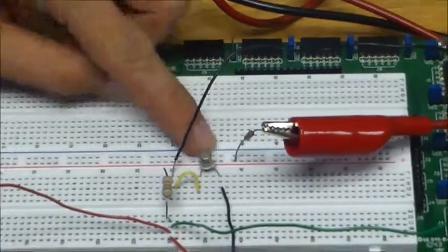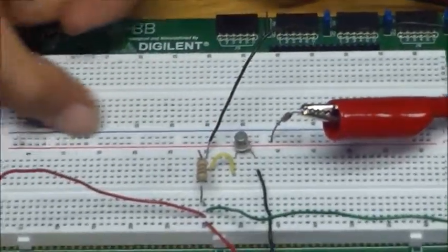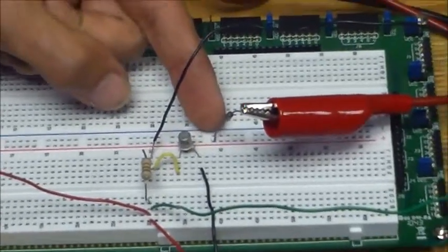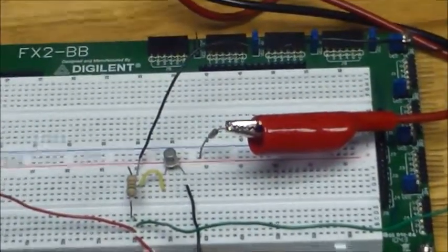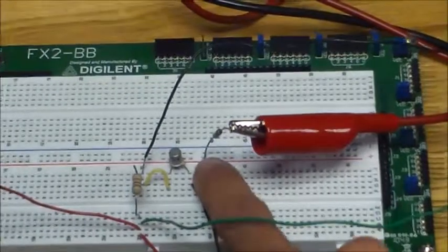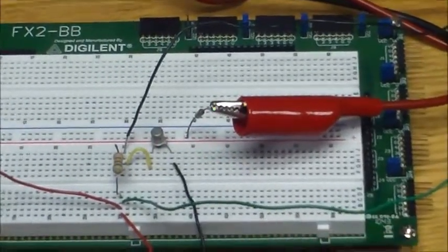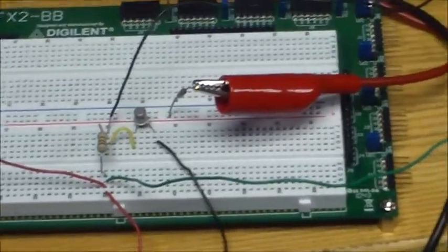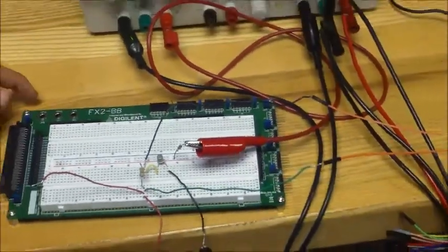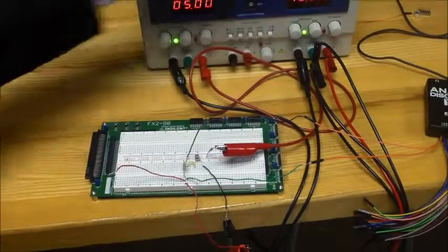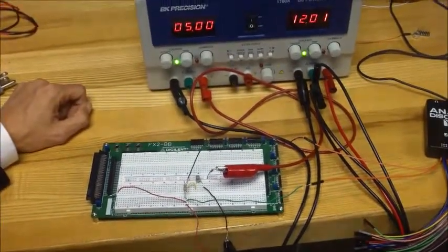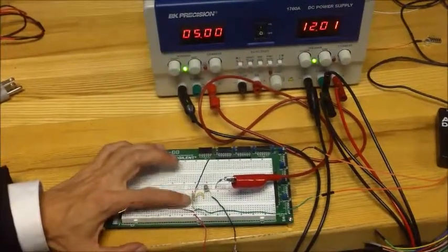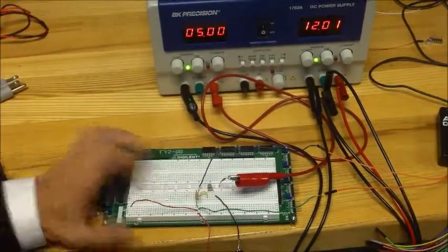We have the base coming into the strip of this test board and out through the resistor here at the 220 kilo ohms. Lastly, this is the emitter leg. This is our ground coming out of that, which goes back to the ground on the power supply. Both supply voltages are grounded, and we expect to see about a 1.8 volt drop across the 5K resistor.